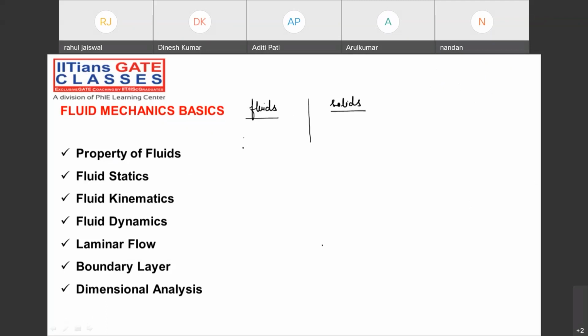So when I take the fluid element as a solid element, but when I apply the tangential force, it will be continuously deforming, right? But why is it not happening in the solid? Why is there a fixed amount of deformation in solids? Suppose this is a solid element with molecular structures. Let's suppose we are applying a tangential force, but it is going to be deformed by the angle theta, angular deformation theta, or shear deformation. Sometimes we say the shear angle.